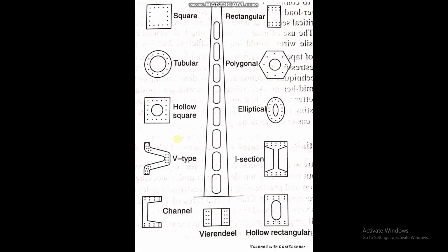Obviously, if we want to design this kind of prestressed pole, we need to understand what the critical loads coming onto it are. Whatever load is coming, we have to design the structure accordingly. We have to find out how much moment is coming, and based on that, we design. Usually these prestressed poles mostly experience wind loads, since it is a tall structure, probably 10 meters or more in height.